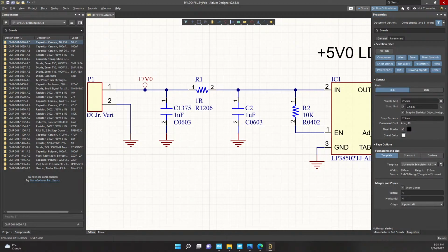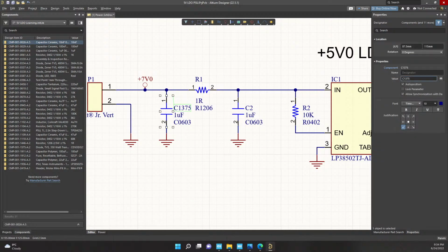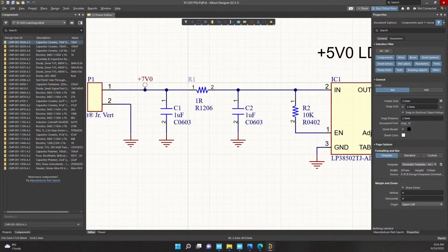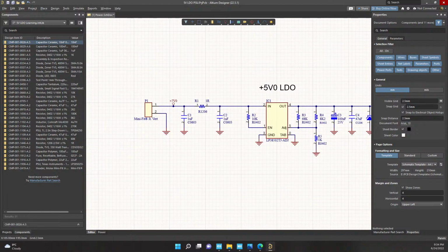Immediately, when you start printing this out on a smaller thing, this becomes a problem, all right? So what you can do here, instead, let me bring it back to C1. You can put this resistor here, resistor R1 designated there, the value over there, and then just like that, so that even if this designator is C1 million, at least it won't confuse you. All right.